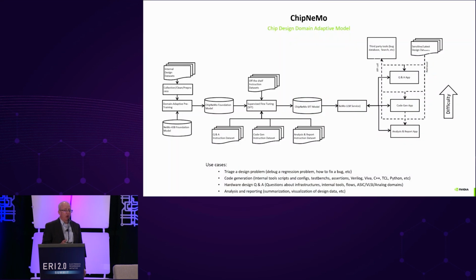To wrap up here, we do use large language models like ChatGPT, and we have the advantage that we have a huge corpus of designs, the Verilog code, the documentation, and all of that. We have internally trained a large language model on more than a terabyte of tokens, and then have fine-tuned it on our own design databases. And we now have a model that we can ask to do things like design the Verilog for a texture interpolator, and it will know what that is and give us a pretty good Verilog design, and we can give it all the constraints of what precision and what speed we want.